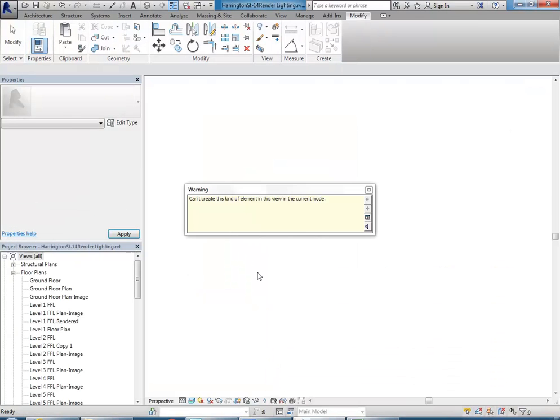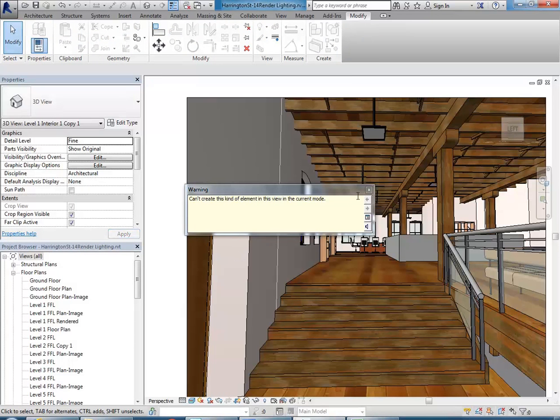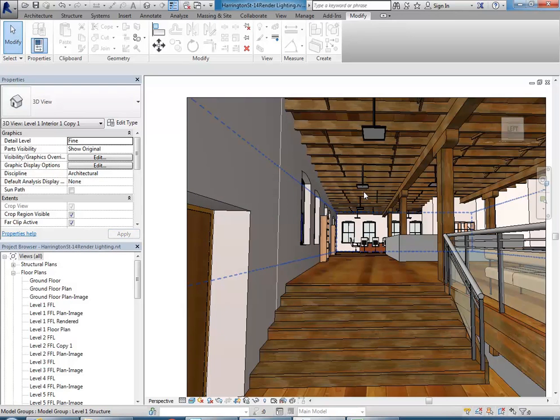But look, the instance where you'll often want to use something like that, and where I really did play around a lot to get another family that I made working, was where I had adjustable louvers. I wanted the louvers to all change angle, so I had a series of like 20 louvers in a window frame, and getting them all to change with just the one angle setting was really important, because I had a massive louver wall basically, and I wanted to get the lighting to come through that and control it with the angle of the louvers, and then set up an animation that had that.